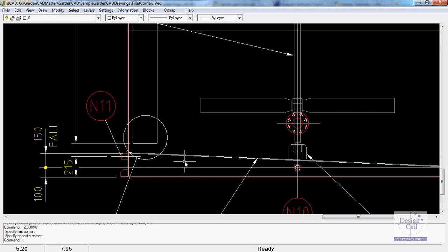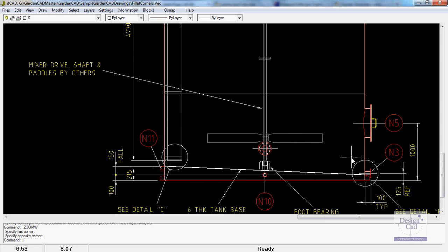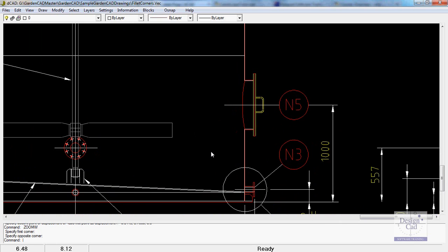100 meters, a certain fall running through here over in this direction. The center of the porthole from the base of the tank is to be 1,000 units up. In this discipline they work in millimeters, so that's 1,000 millimeters up from the base of the tank will be the center line for the porthole that will allow fluid to escape from the tank when it's released. So can you see you draw with precision in the majority of disciplines that we use computer-aided design in?